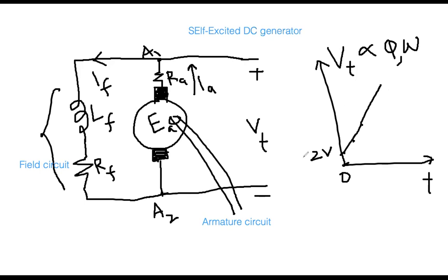Now, everybody look: if you notice that nothing is happening, you are always getting 0 and 0. You connect a voltmeter at this point and this point, but always get 0 volt, meaning this circuit is not working, because there is no remaining flux.